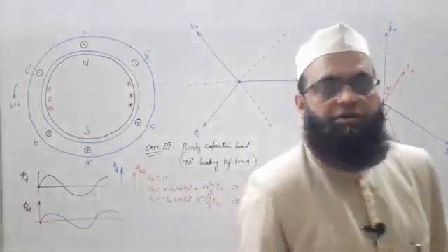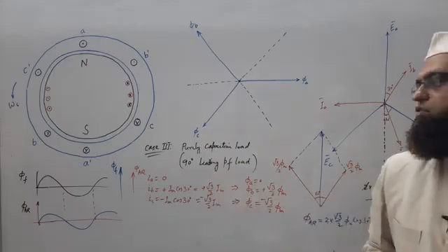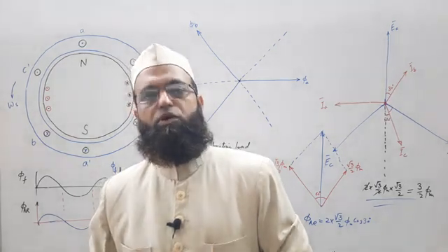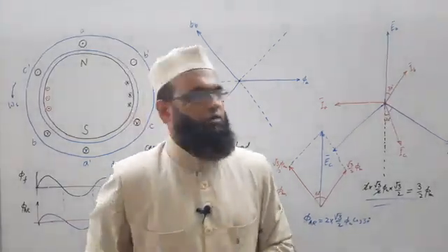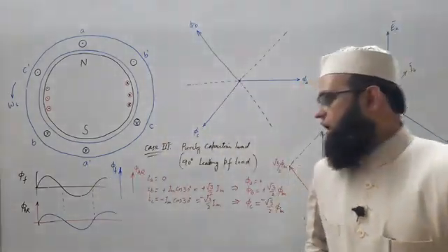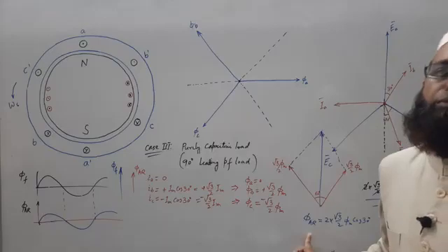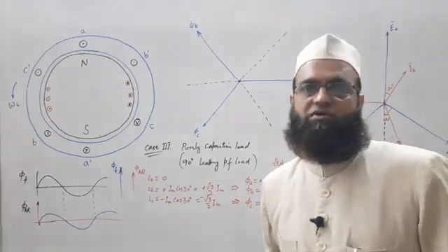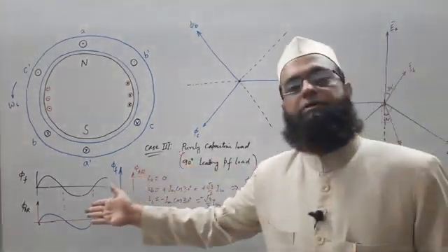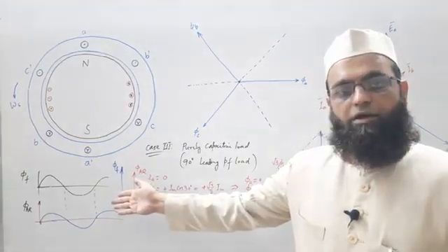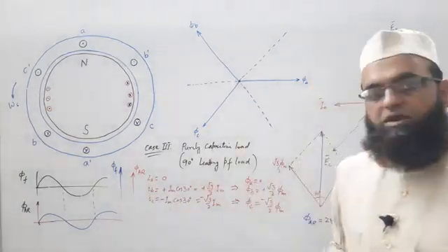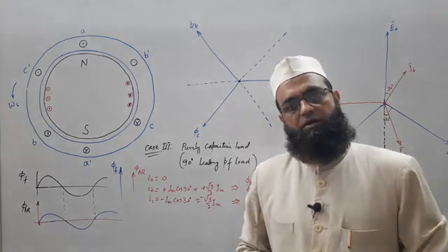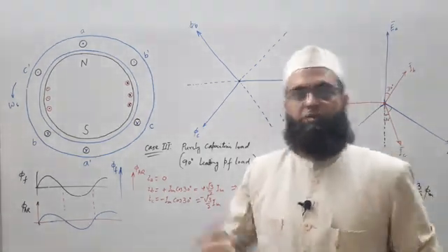So we have discussed this case also, and this effect is known as the magnetizing effect, purely magnetizing effect. So we have discussed the various natures of the same phi AR. Sometimes it is the culprit, in case of purely lagging, always opposing the main field flux. Sometimes it is very friendly, a very true friend, ready to help at every moment in this case. And in the previous case, cross magnetizing effect in case of purely resistive load, where sometimes it is helping, sometimes opposing, cross magnetizing.